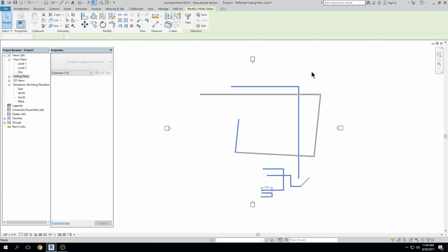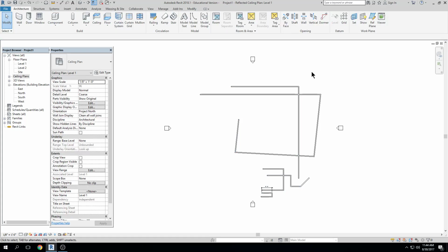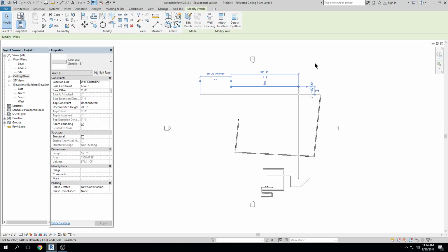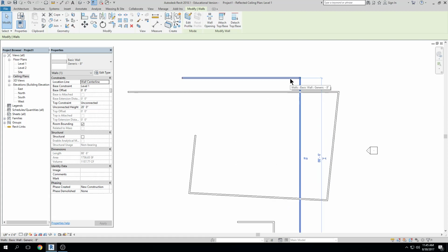Okay, escape, escape. I also have a pick where I hover over an object, it turns blue, it highlights, and I click on it, and I've selected it. Now in AutoCAD, if I pick something else, it's additive. I can add objects every time I pick on something. In Revit, if I pick something and then I click on something else, it deselects the first item and selects the second item. So click, click, click. Now this is probably my most annoying pet peeve between AutoCAD and Revit.